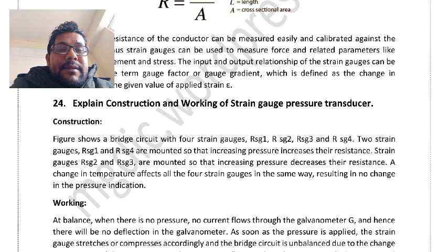A change in temperature affects all four strain gauges in the same way, resulting in no change in the pressure indication.